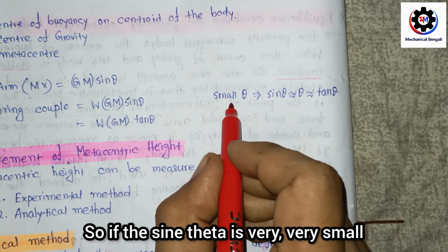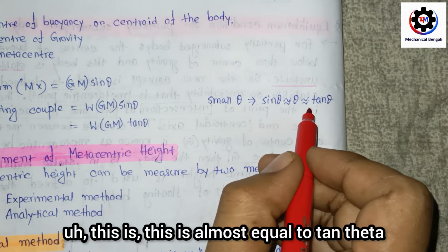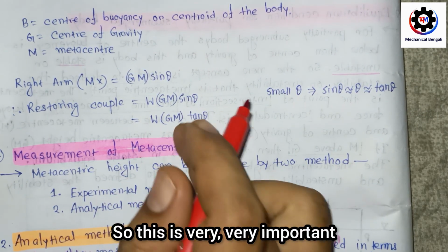If theta is very small, sin theta is almost equal to theta, or tan theta. So the restoring couple will be W GM tan theta. This is very important.